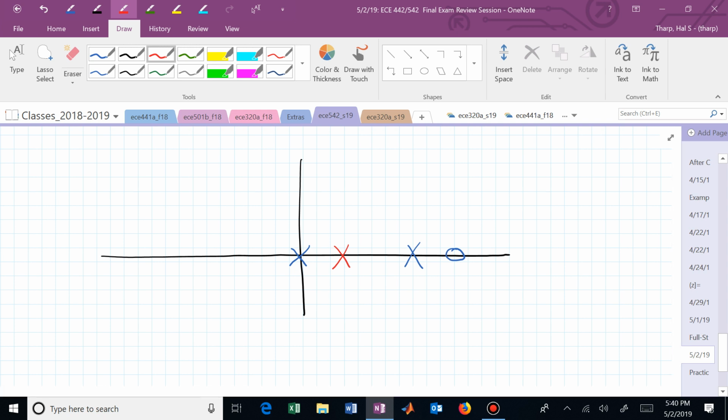Why did we put that 0 down to begin with? I better remind us where we're at. That doesn't help, does it? Because we're stuck between 1.5 and 2 with that branch. No, we don't break away from 1.5 to 2. We're just locked onto that real line with a branch of our root locus. If you looked at K between that, what's going to happen? K is going to just be monotonically increasing from the pole to that 0. Even if you break away, so you're saying you're breaking away here. Whoops, how did I get black?